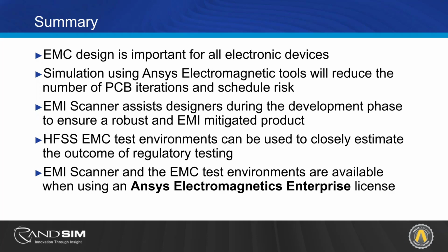If you want to take it into the full simulated test setup, you can bring that into the HFSS EMC test environment for a very accurate estimate to the outcome of regulatory testing prior to even fabricating your board. And it's important to mention that to access the EMI scanner and the EMC test environment, you will have to leverage an Ansys Electromagnetics Enterprise license.